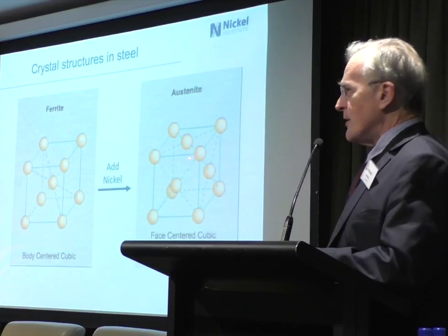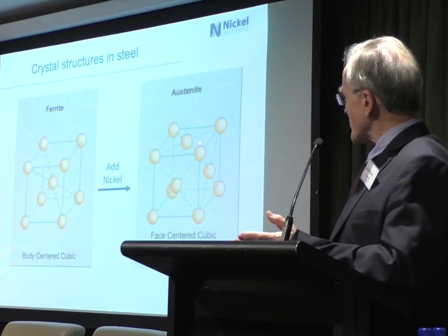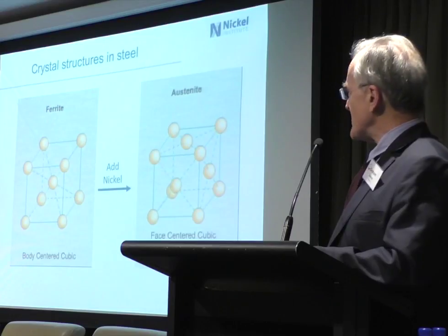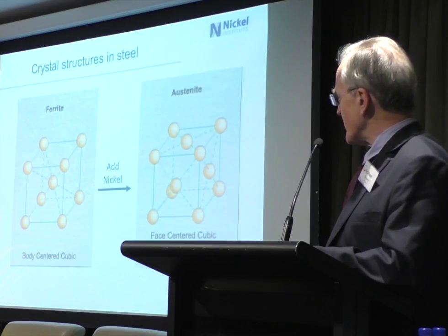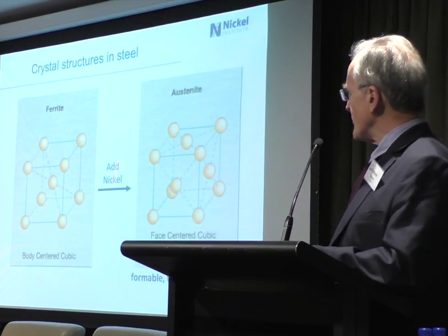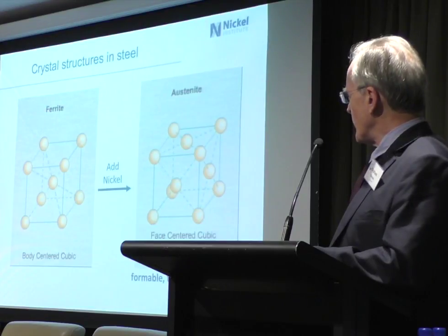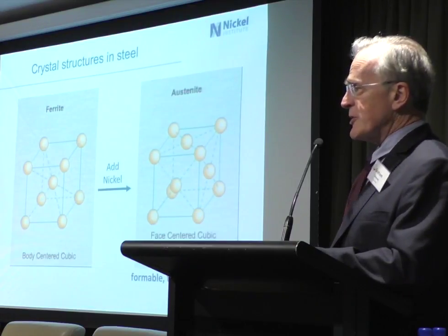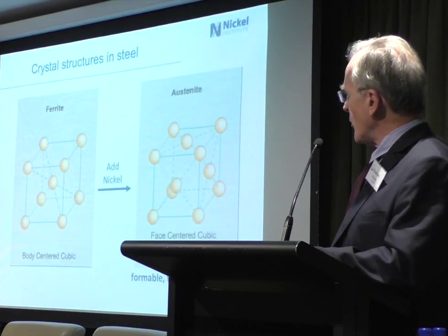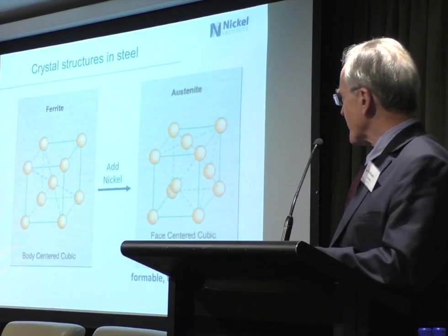Austenitic. You know what austenitics are like. They're easy to form. And it's just the structure. I mean, you push on the corner, it moves in. There's absolutely no bracing across, whereas there's lots of bracing here. And, okay, it's formable, it's tough because you push it and it recovers, and it's weldable. Doesn't matter so much at the moment, but really it's just a matter of all the rubbish atoms that are around when you weld are going to get hidden inside this cathedral of a hole, whereas there they can't fit in. They tend to crack when they squeeze into the gaps.